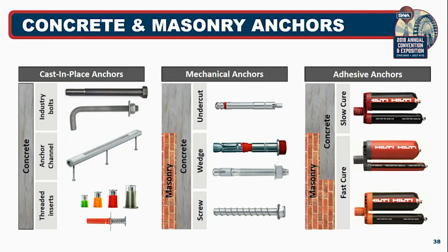And then also the temperature range at which it can be utilized. So some products can be used at much lower temperatures than other systems. Certain products, I have seen adhesives out in the market that the minimum temperature at which it can be utilized is 71 degrees Fahrenheit, which for us in Chicago is almost never. And yeah, so that's something else that needs to be taken into account.